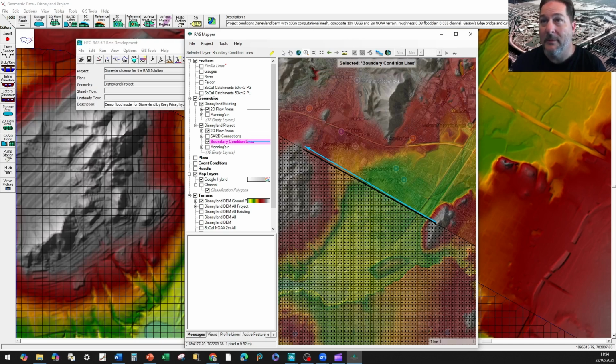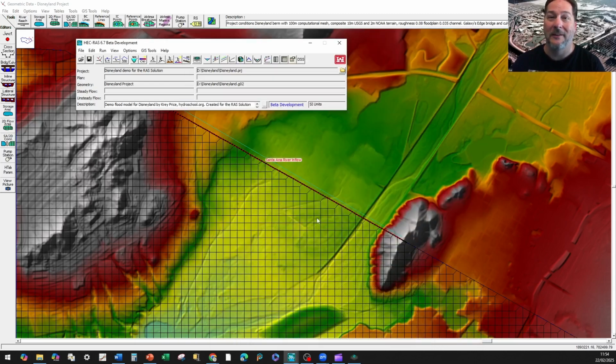And again, you could flip that around, but if you started measuring flow inside of the perimeter itself and started drawing profile lines here, you could orient those either way, and it's just going to assign the positive and negative flow direction. Negative flow doesn't mean it's wrong, it just means it's in the opposite direction of the assumed positive flow direction. I picture these black and red lines being perforations in my perimeter.